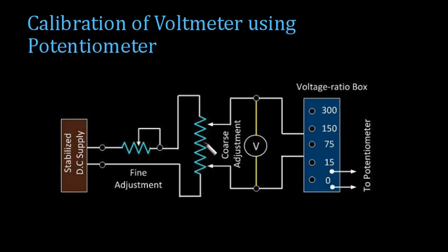Once we make the adjustments at the sine and cos levels and get a particular reading, then you move towards the potentiometer to measure the voltage at this particular point. You can see that the voltage indicated by the voltmeter will be across these two points, and the same voltage is also measured after reducing the levels. So the potentiometer will be giving the true value.